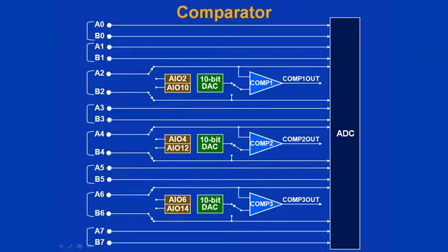This device has 3 analog comparators that share the input pins with the analog to digital converter module. If neither the ADC or comparator input pins are needed, the input pins can be used as analog I/O pins. As you can see, one of the inputs to the comparator comes directly from the input pin, and the other input can be taken from the input pin or the 10-bit digital to analog converter. The output of the comparator is fed into the EPWM digital compare submodule.